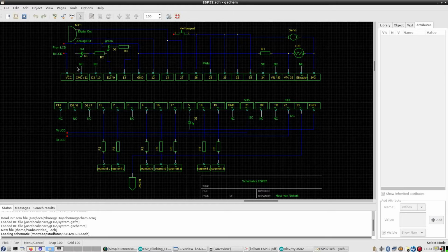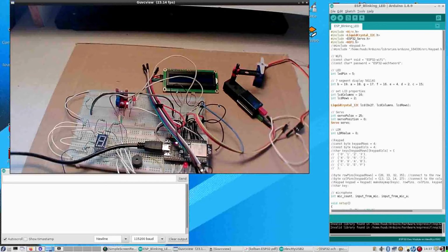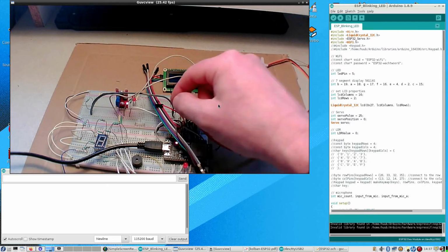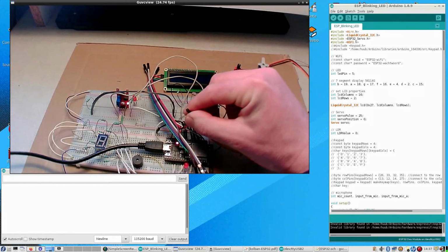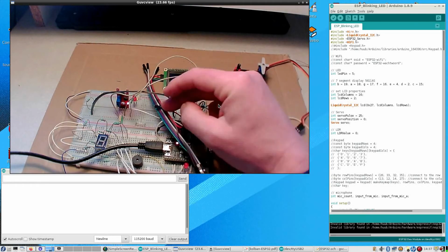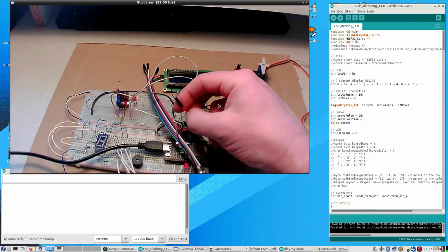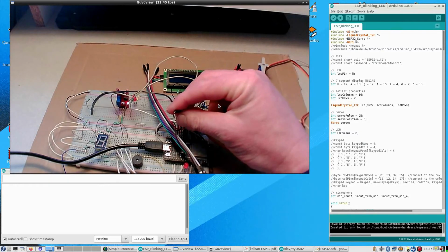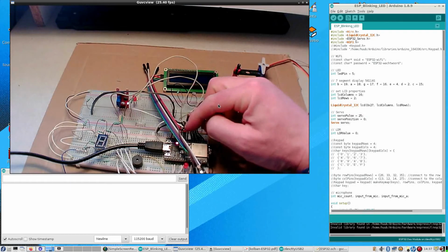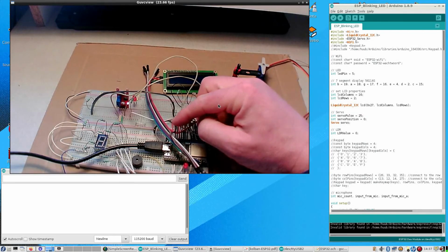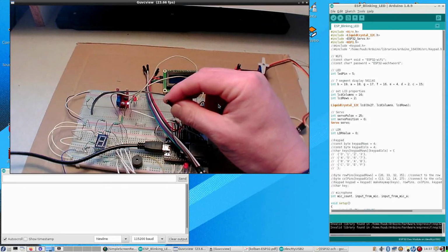Ouch. And then by accident the LCD problem is solved. The point is that this wire used to be the power for the LCD, which was just loose. So why was that loose when this black one is the ground, red one is the power?